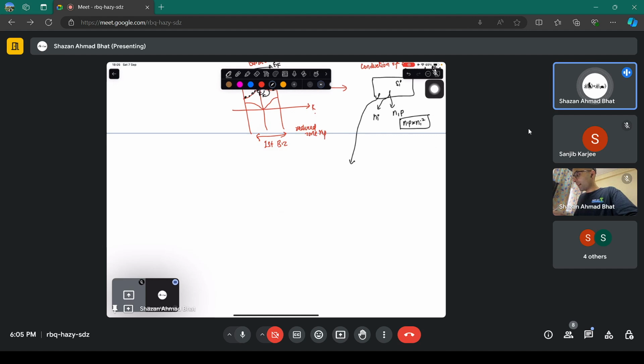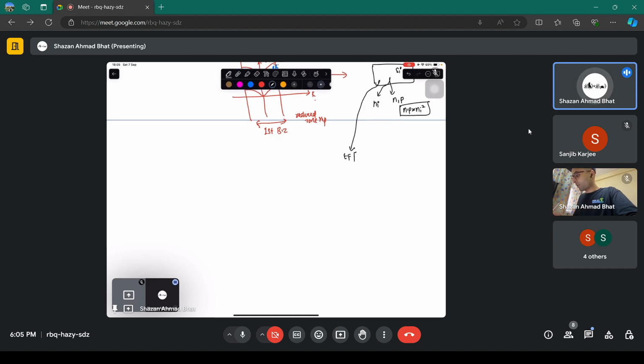Now you showed what happens whenever you apply the electric field, you have a bending where electron and hole pairs are generated. You also know that this electric field is equivalent to the spatial gradient of the energy level, and that's why you have the band bending if you apply a potential to a semiconductor chunk.